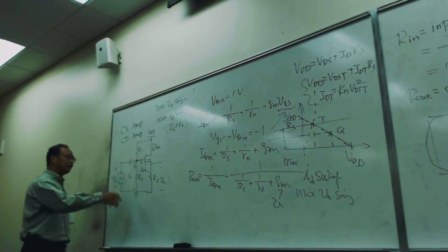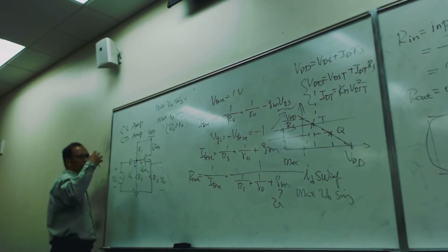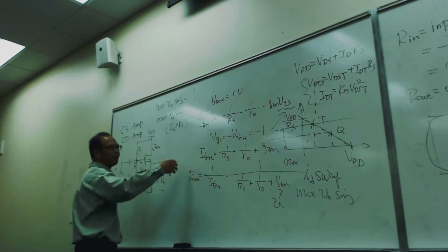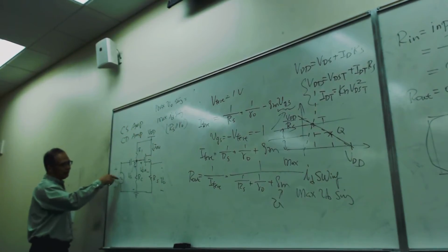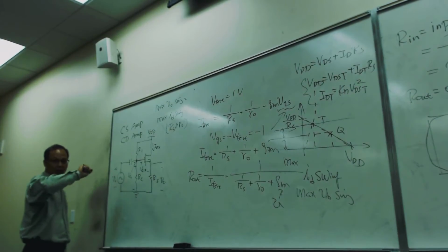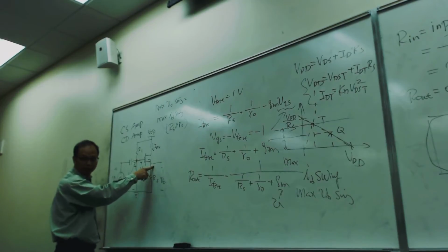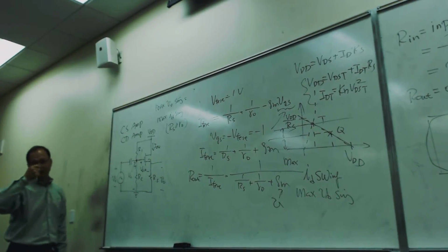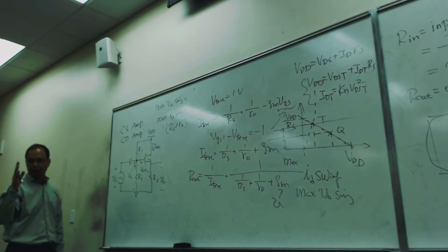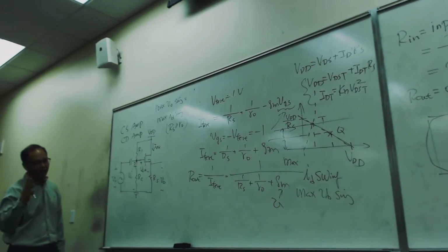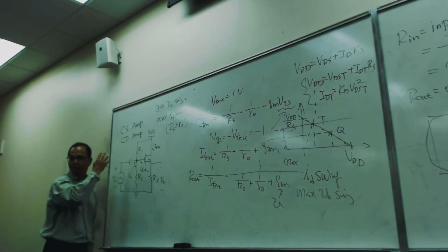So basically, you have a circuit like this. How do you correlate the measurement with what I have shown here? You have an input source. You can increase the input source and look at the waveform at the output. You can increase until you start to see distortion. That is the moment of the maximum output voltage swing.